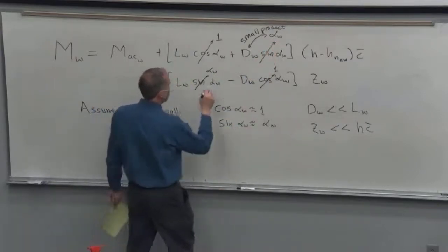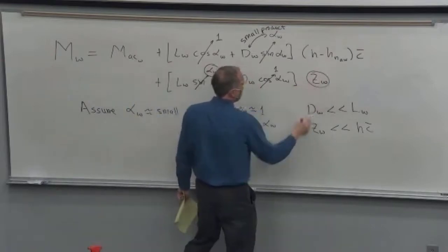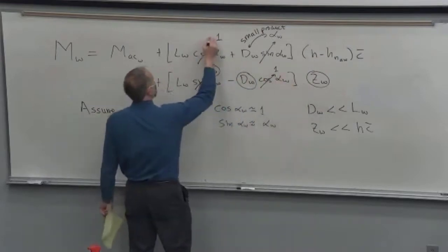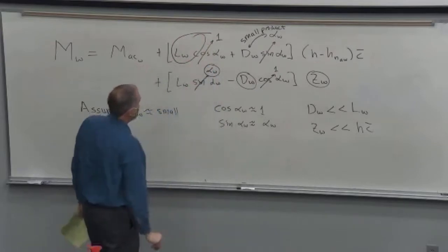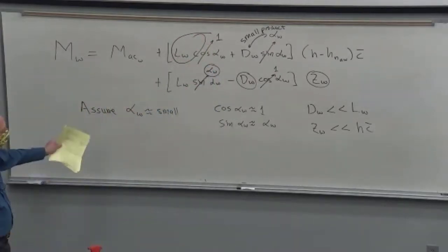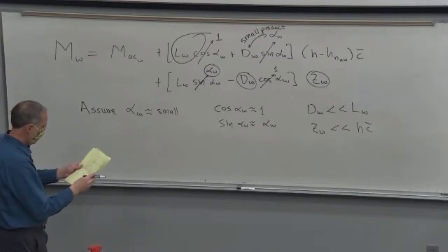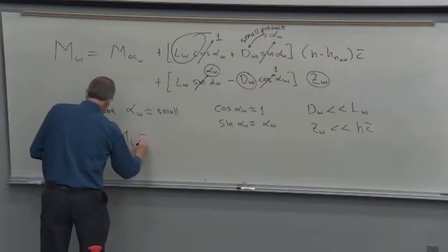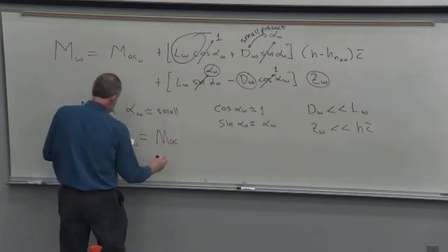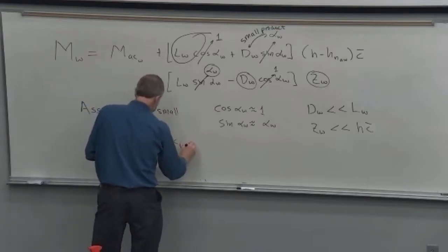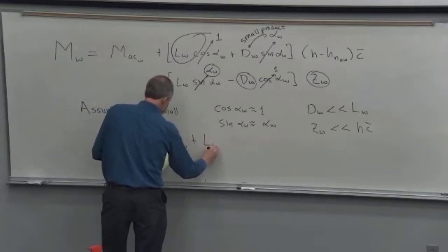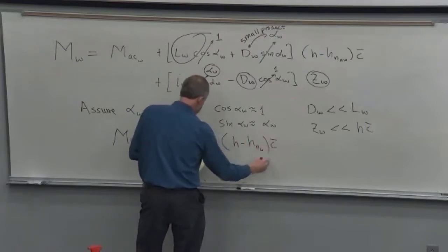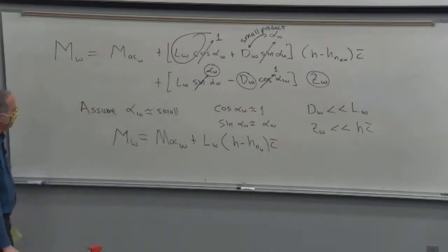And the same thing on here. Here we've got a small number times what we said is a pretty small number. And same deal here. The drag we said was small, lift. So really we're going to say, well, this term right here is much bigger than anything else for small angles of attack. So these kind of cases, this is all we have left. Like that. So we've simplified it a lot.